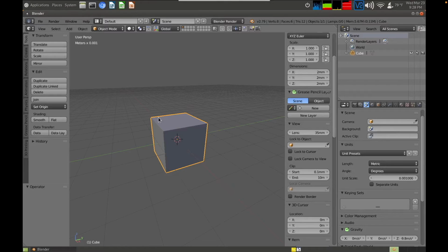All right, the 3D view has a bunch of modes, but the one that we're actually going to cover is the edit mode. So there's a sculpt mode, vertex paint, weight paint, texture paint, but for hard surface 3D modeling, for 3D printing, edit mode is what we'll mostly be using to make our primitive objects more complex. So to get to edit mode in the 3D view, you can just press Tab.